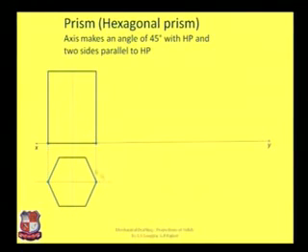Take projections and draw projection lines, and make a rectangle over here of the given dimensions. Name these points A, B, C, D, E, F like this, and draw projection lines. Here this is the front view of this solid. This line B dash to this will be visible, it will be a full line, this will be a full line. Here is the center line, here is the center line.